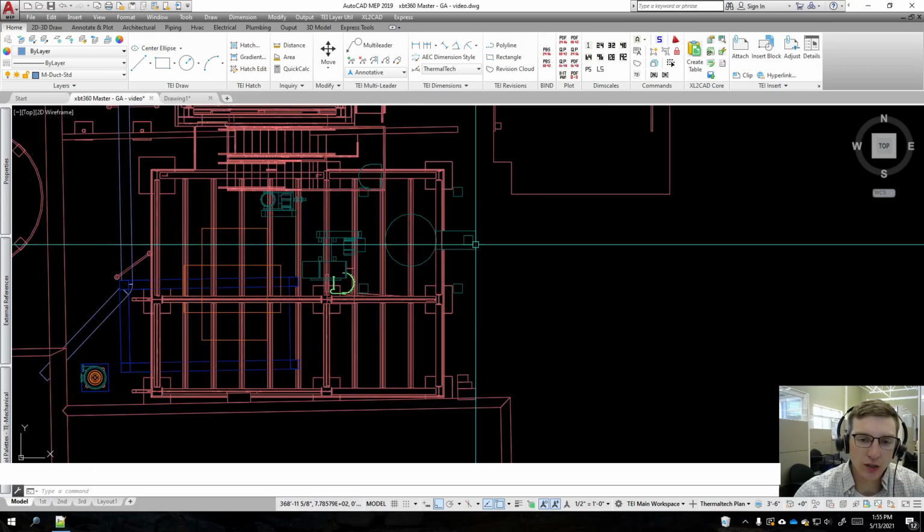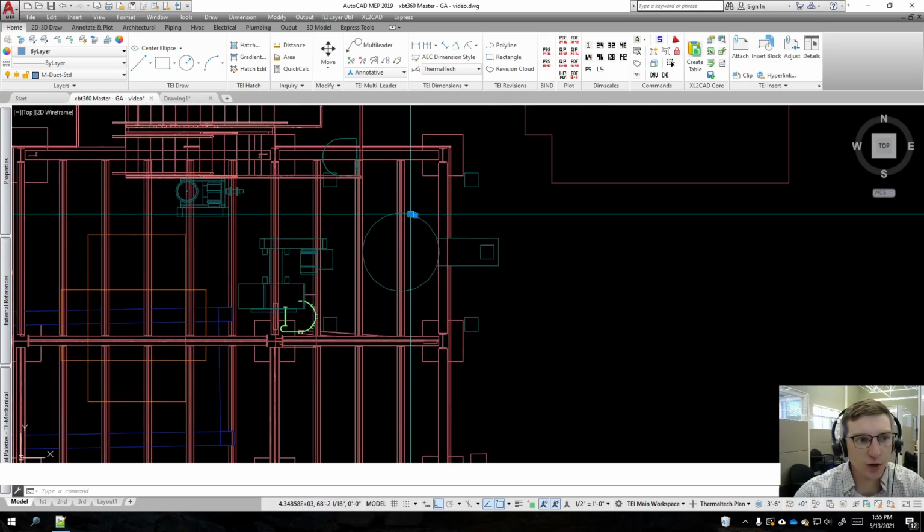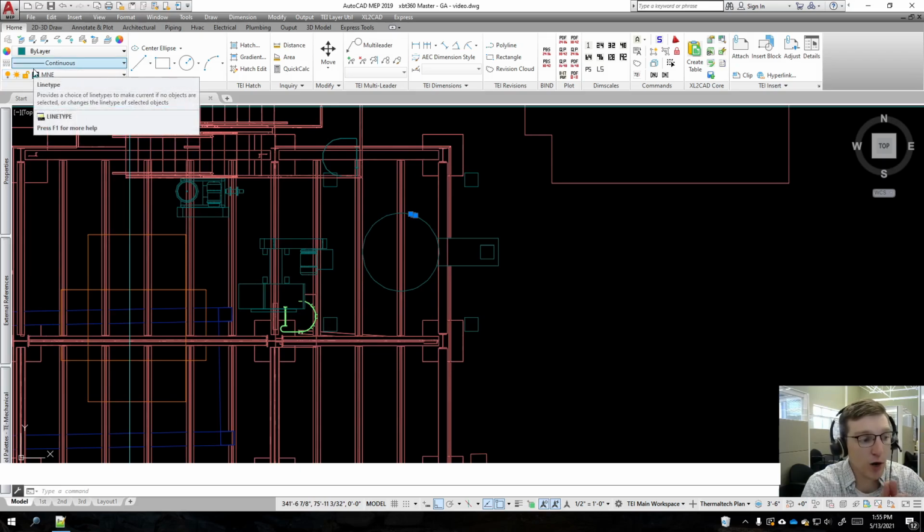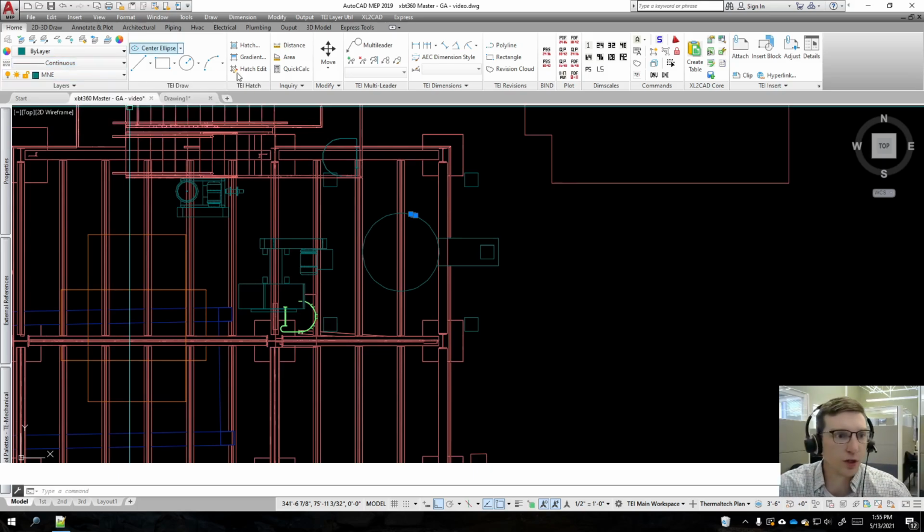All right, and once it's done, we click on this, and you can see that it's now just on straight layer M&E. So it's truncated everything prior to that. Now, if you need to edit this and still retain the majority of the xref name that it actually is, because you need to target things differently, that's totally doable. The code's editable, so you'll have access to that. You would really just look for the key character that divides it and get rid of that. But that's a conversation for another time.